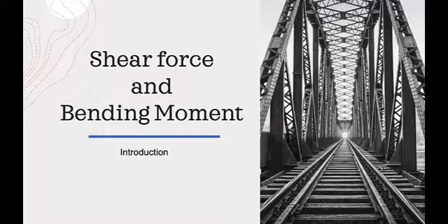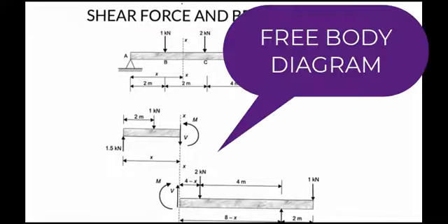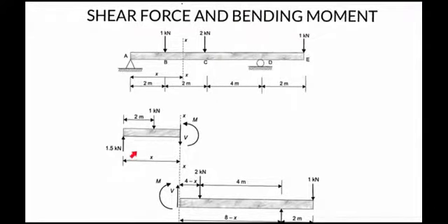Shear forces and bending moments are internal forces and internal moments in beams. In the given free body diagram of the beam, for equilibrium of this part, a force V and a couple whose moment M must act at the section. The force V and the moment M are the resultants of the forces distributed over the cross-section. In the FBD of the isolated part of the beam, V and M are considered to be external forces. However, for the beam as a whole, they are the internal forces at section X.